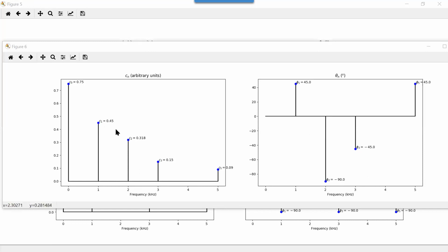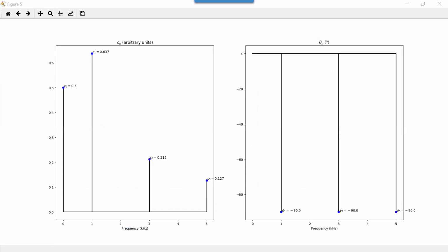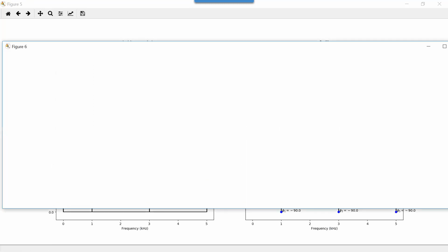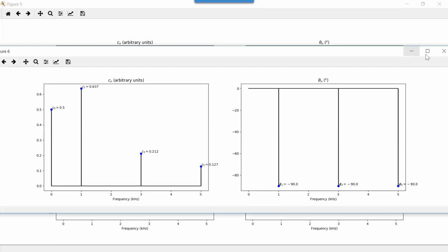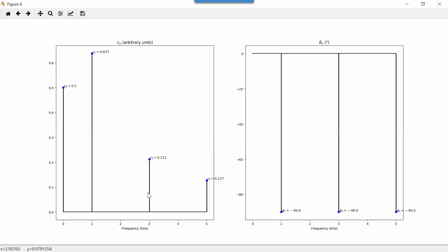So these harmonics will be out of phase, and so they just don't add as well. So really, it makes it easy, because in order to test this, you only have to put in a 50% duty cycle square wave, and you can go from there.